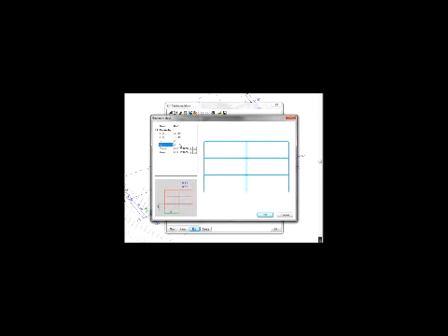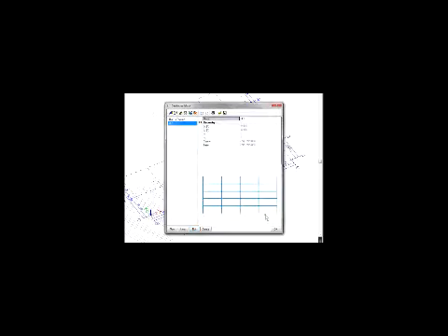In the properties dialog, you can see the properties that make up this frame: its height, the number of bays, columns, cross-sections. If you need to make it a little longer or taller or change the number of bays, you don't remodel it, you simply edit its properties by typing in new values into its dialog box.